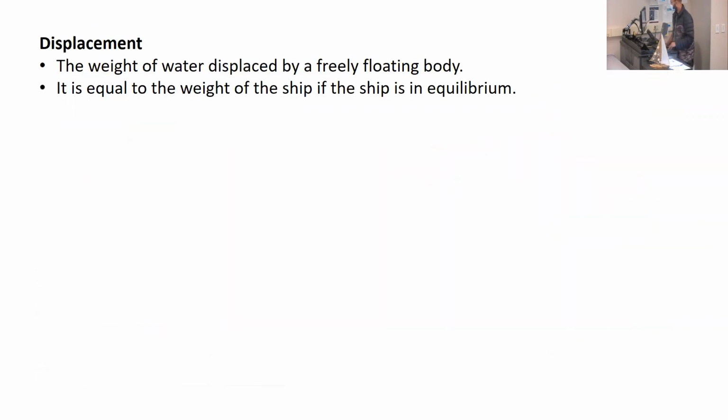So another important term you'll encounter is displacement. The definition is the weight of water displaced by the body. When we are in equilibrium, what can you tell me about displacement? When you're in equilibrium, the weight of the ship is equal to the displacement. If it's not, you will either rise up or sink down until this equilibrium is attained.